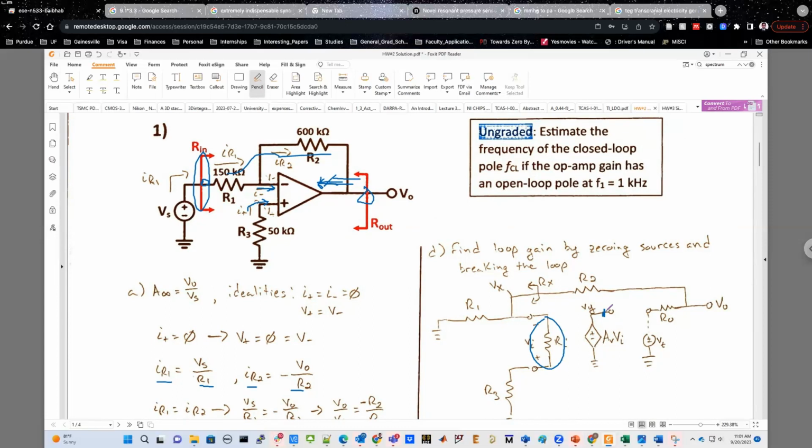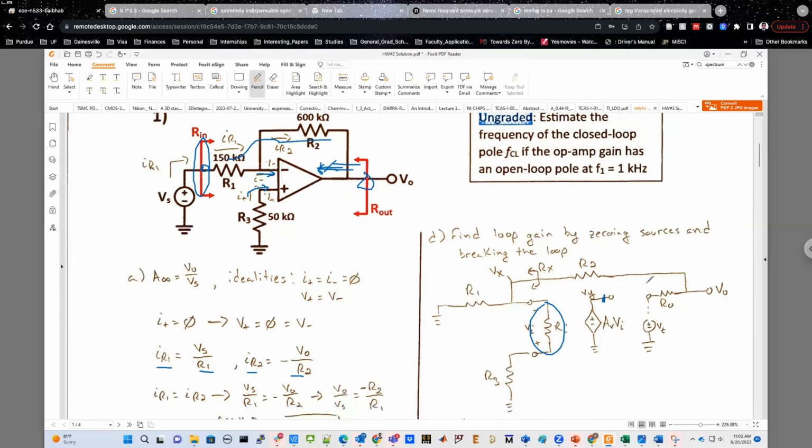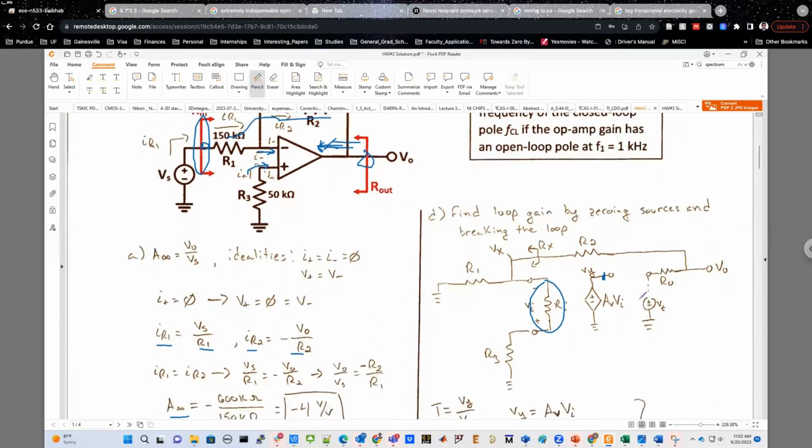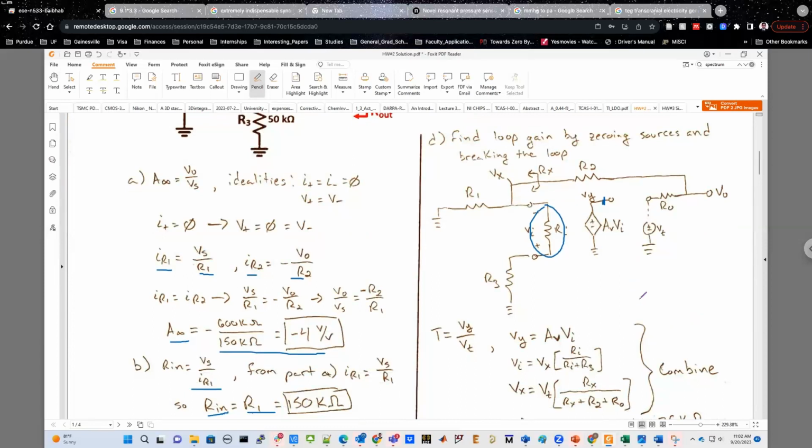And that is true for any feedback circuit. For feedback, you're taking the voltage from the output and putting it back at the input side. So what is the gain for that feedback? The gain for that feedback is whatever voltage is available at the input side divided by the voltage that was available at the output side. So that's the feedback gain. Feed forward gain is the reverse. Now again, you can solve the voltage divisions that are there, and all of you have already done that in your homework 2 solutions. Questions?